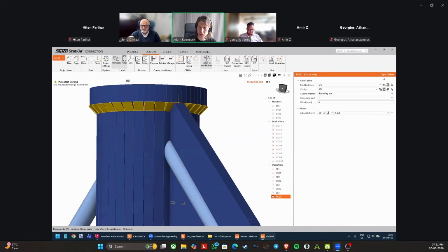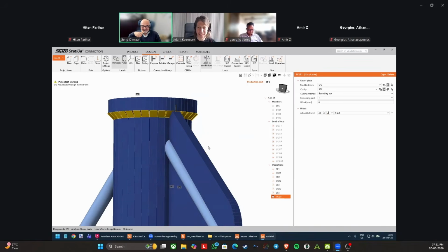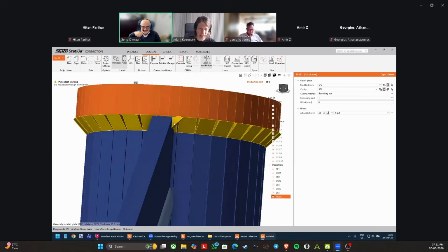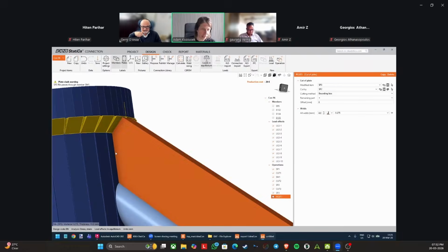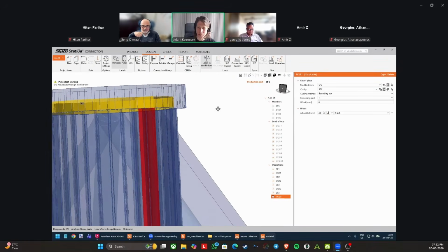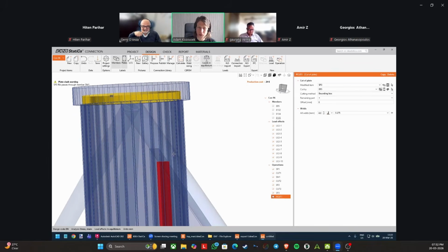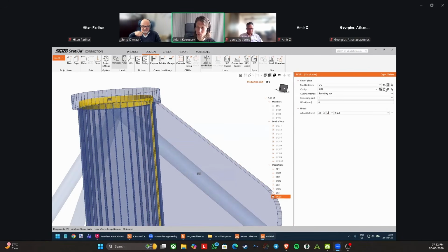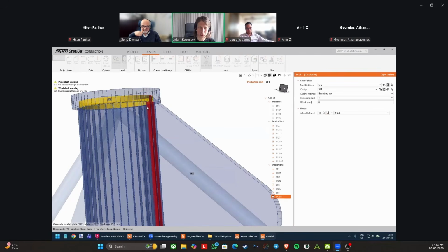No. First I showed you cut by member, and then I switched to cut first by this plate. Okay, and I will finish this one, and I will add another one between here. So I just wanted to show you that you can switch and choose like this, and you see that the clashes are removed here or here.